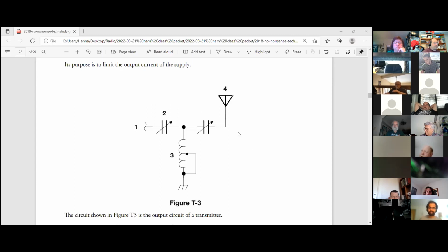There's nothing that new here, except that we also said that an inductor looks like a short circuit for DC and an open circuit for AC. And a capacitor looks like a short circuit for AC and an open circuit for DC. Well, because once it fills up, it doesn't have anywhere to go.